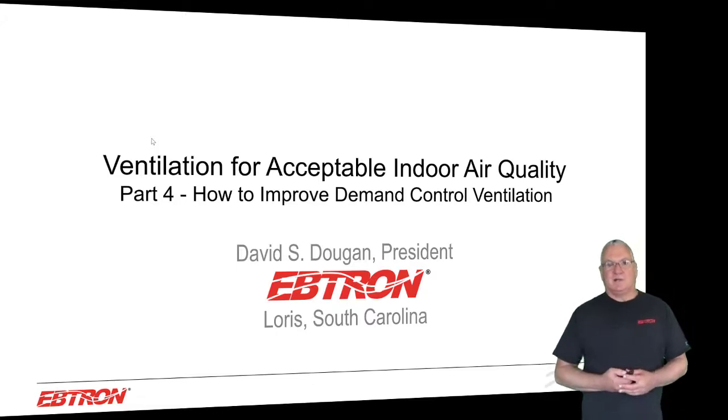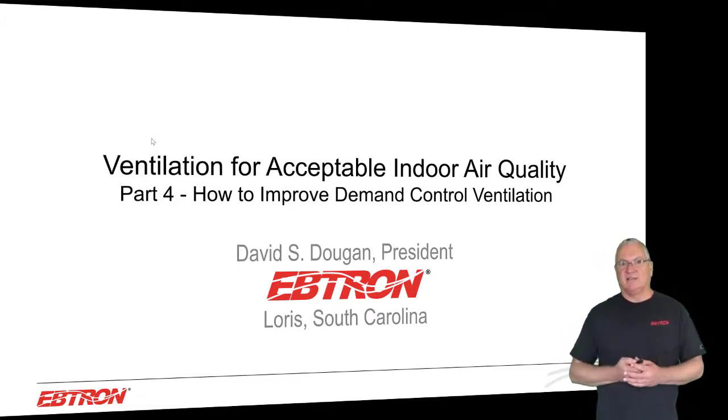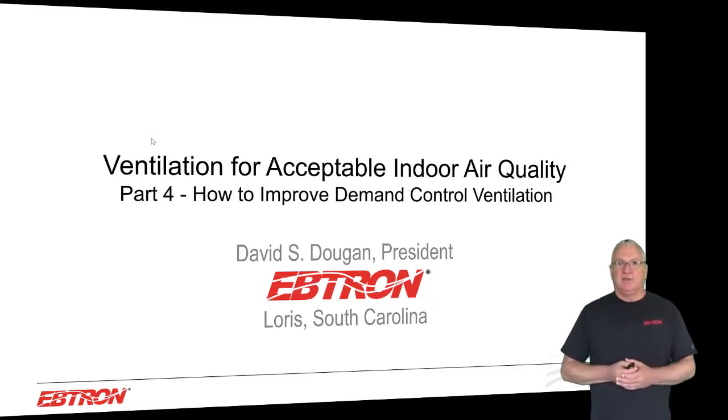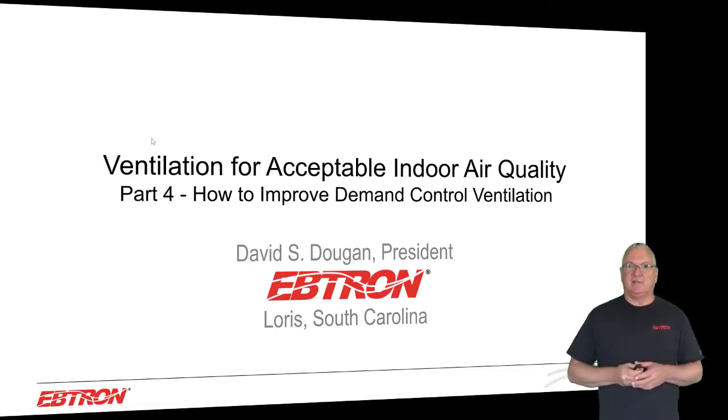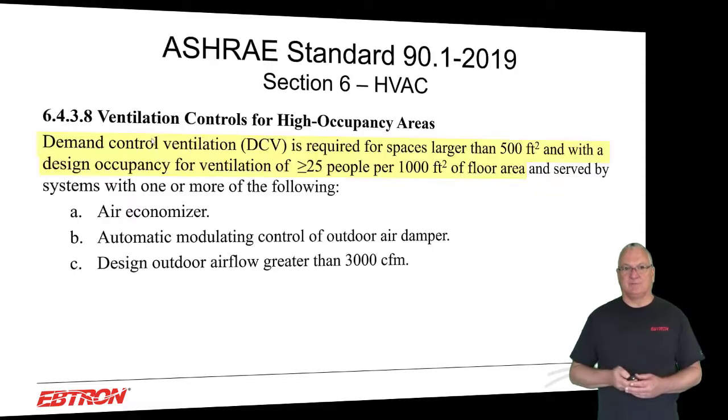This is part 4, how to improve demand control ventilation. If you had actually used this strategy, which a lot of folks have, but not enough of them, you'd find that during COVID you'd be able to easily switch over from DCV to ventilation for what I'll call pandemic mode. This is just a solution that I think we should do going forward for DCV. It still will save energy, but it also will make sure that you provide proper ventilation. I think that's what's really important.